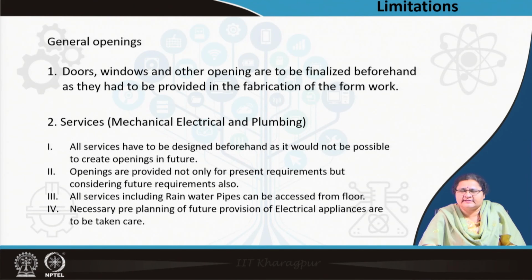Coming to the services, as I told you, the MEP, the mechanical, electrical and plumbing, all services have to be designed beforehand, as it would not be possible to create openings in future. Say in the floor, there should be proper holes to receive the pipes. On the wall, there should be proper holes to receive the outlets, overflow pipes. So, you will have a wet area. So, you are actually having a very prototype design.